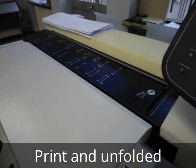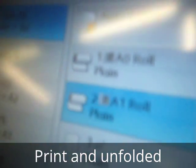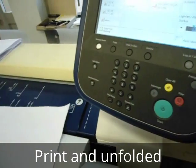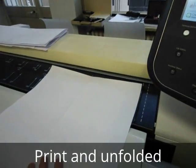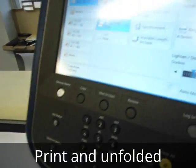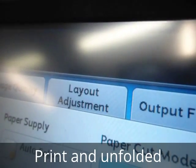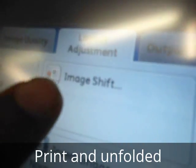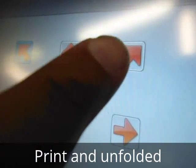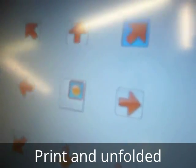If we have a document, like an A2, that does not match the paper rolls, since we have A0 and A1, we can print the document, but we need to justify according to the title box. So we don't have a paper roll 420, but we have a paper roll 594. So we can select always A1 rolls, but then we have to go to layout adjustment, image shift, corner shift, and then we need to select upper right corner in order to enable the non-standard size to be correctly aligned to the top right corner.